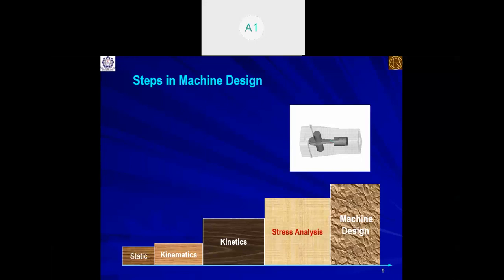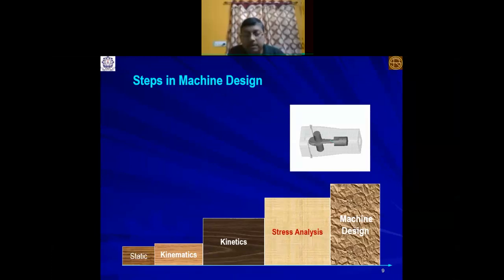This is the stress analysis. You know the material; you already select the material and boundary condition. When you apply the boundary condition, you do stress analysis using CAD tools or whatever it may be. You select the material and take the material properties from the data book. Allowable values of the mechanical properties you also have to assume, or, being a designer, select by considering a suitable factor of safety. You know the allowable stress limit.